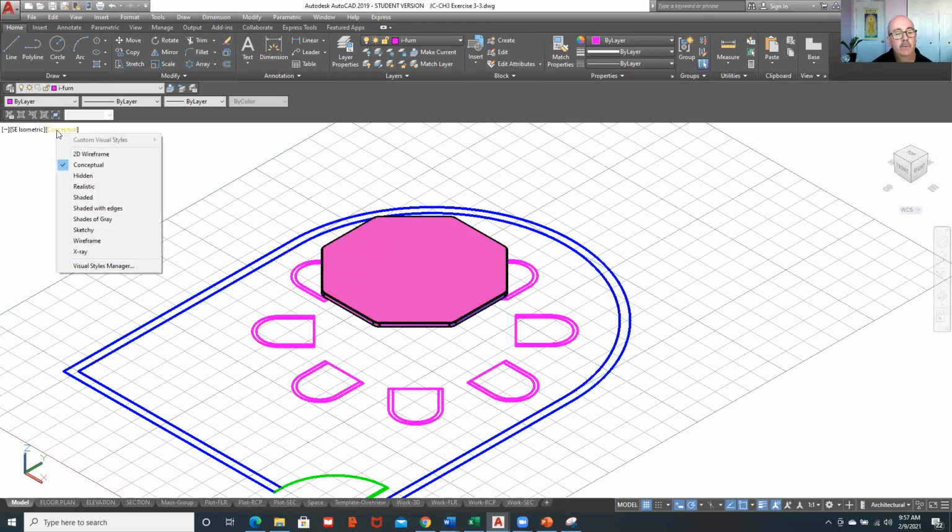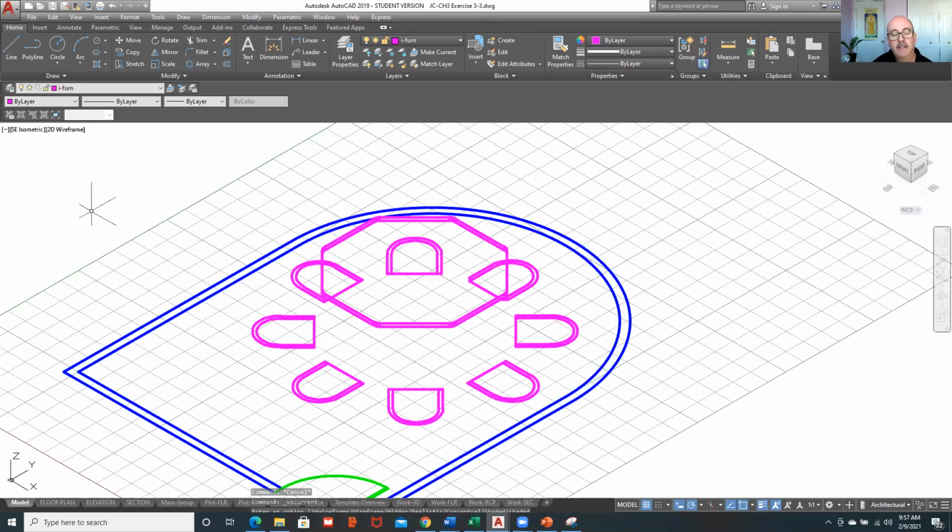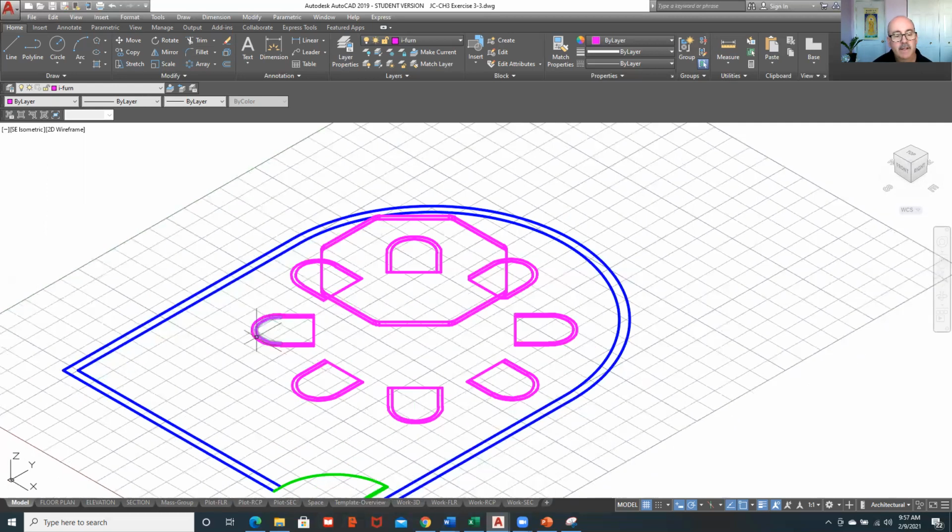And as I start to work with them, I'll toggle back and forth between 2D and 3D and do things like creating in the center of it, if I can get my O-snaps to grab. So I don't have a center because it's a polygon. But I would put a pedestal in here into a table.